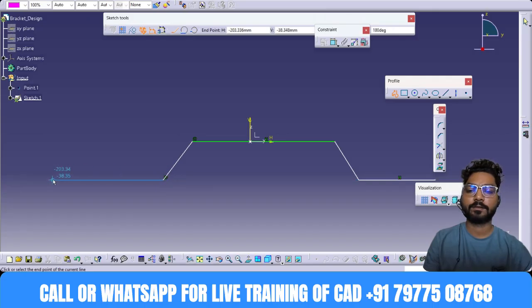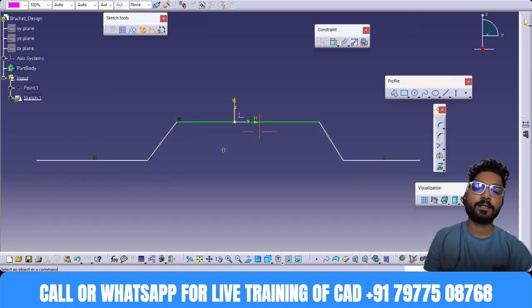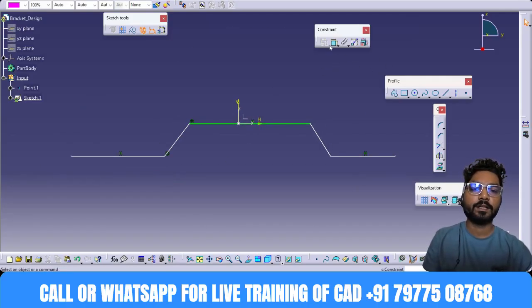So this is our concept, the sketch we are trying to create. Then we'll do the positioning: this point and this point, right click, make symmetry to this. Then we'll do these two points also, and then these two points also we'll make symmetry.